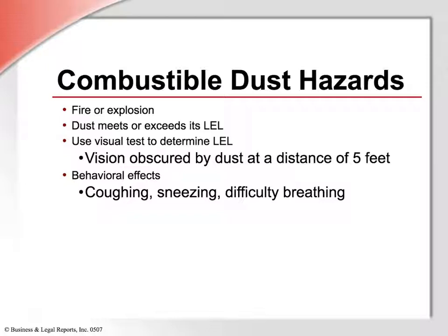The behavioral effects on entrants include coughing, sneezing, and difficulty breathing if not wearing appropriate respiratory equipment. If wearing appropriate respiratory protection, behavioral effects will not be noticed, so the space will need to be visually monitored continuously to determine if the dust obscures vision at a distance of 5 feet.